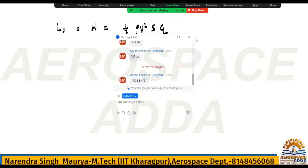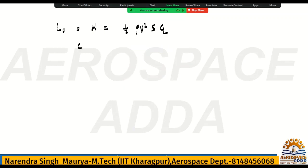Yes or no? So what is the CL? Remember, this is L naught, hence this velocity will be V naught. There should not be any confusion. And this density you need to calculate at 3 kilometers. So what is that ratio they have given to us? Rho upon rho naught, check that ratio they have given, 0.742. What is the density at 3 kilometer altitude?